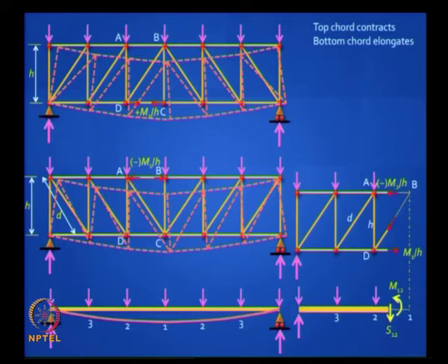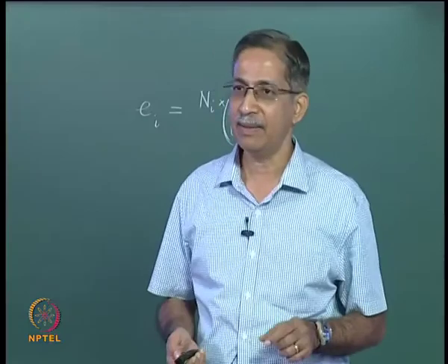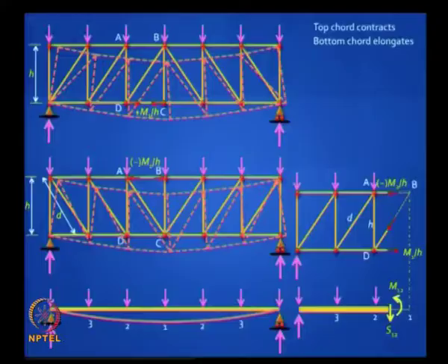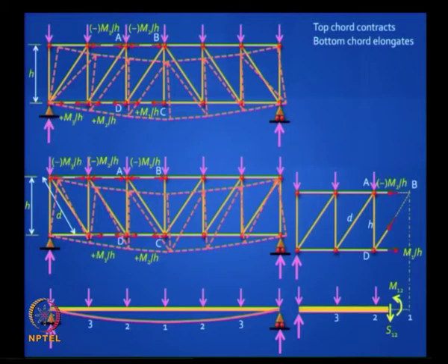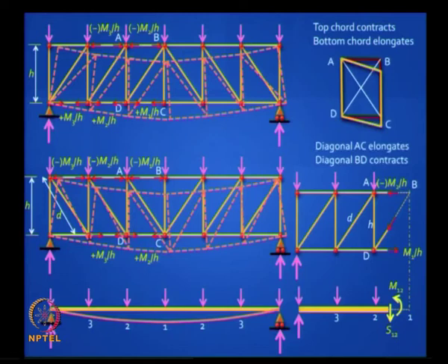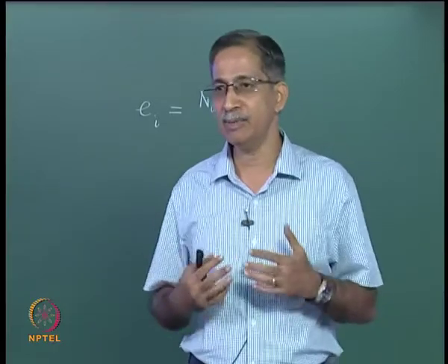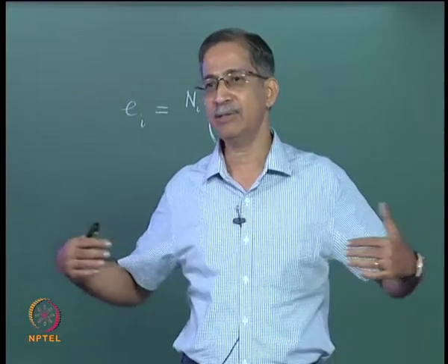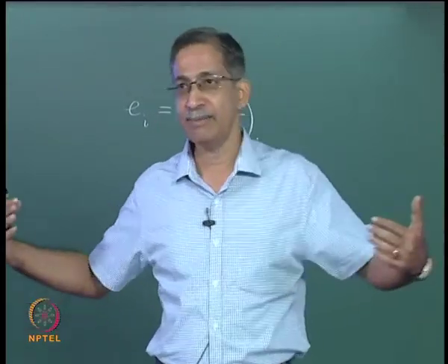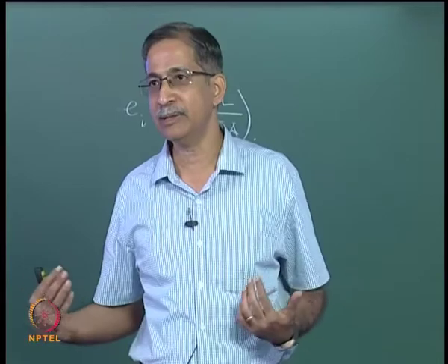If you had to design a truss quickly, you can do it very fast. Find out the equivalent bending moment in a beam, divide by the height. This is how you can work through the different axial forces in the top chord and bottom chord. The axial forces will be maximum in the middle, just like the bending moment is maximum in the middle region, and it slowly dies down, and sometimes your end members will carry zero force.